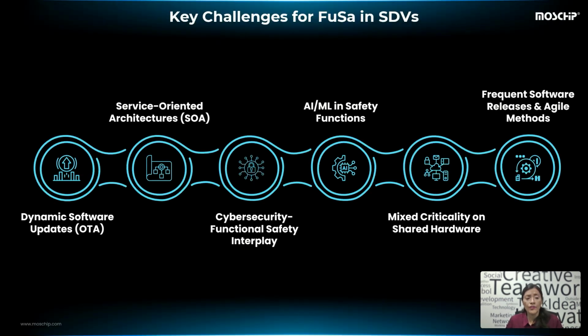So by now, we must have got some idea of how SDVs are posing challenges for traditional FuSa. So let's bring everything together and summarize the key challenges here and how they are impacting functional safety. SDVs have dynamic software updates, and ISO 26262 is rooted in the V-model, and it wasn't designed for continuous deployment or field updates. Any change might affect existing mechanisms, invalidating previous safety validations.